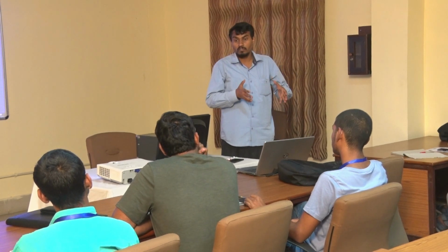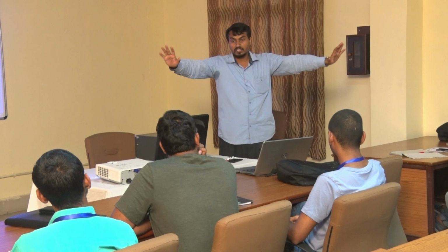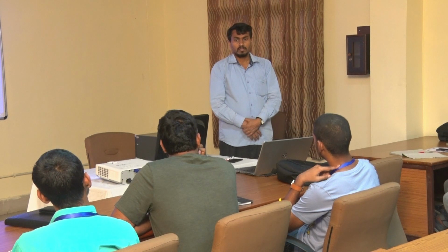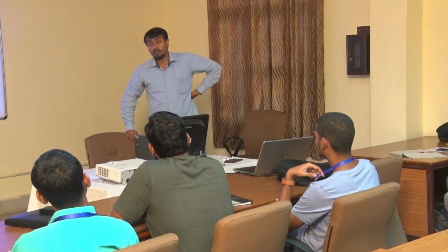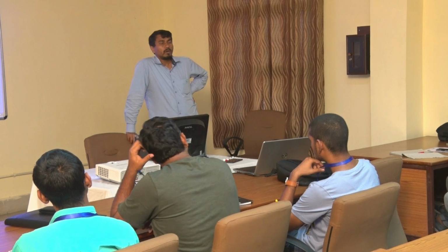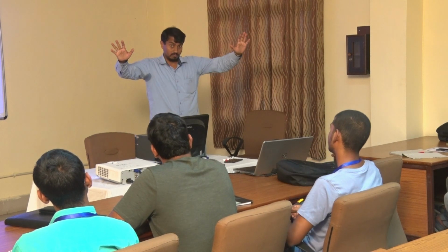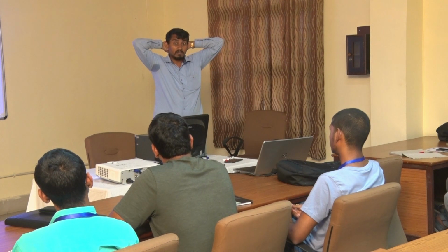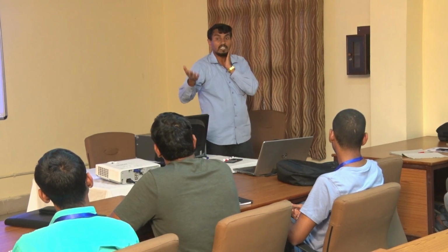For a small slope face, it is possible that by laying the geosynthetic grid, you can do a good amount of job. While I was in IIT Kharagpur, we were associated with this kind of work, and we saw that for a small slope, suppose 10 meter up to 20 meter, 30 meter high in total, there is a bench. Here you can think about that. But beyond that, in mining, we are generally now working at 90 meter, 110 meter, 120 meter heights.